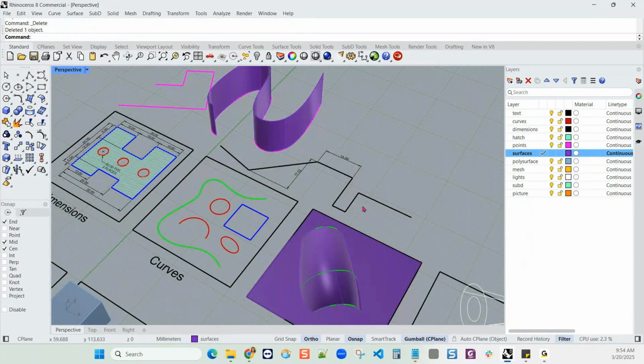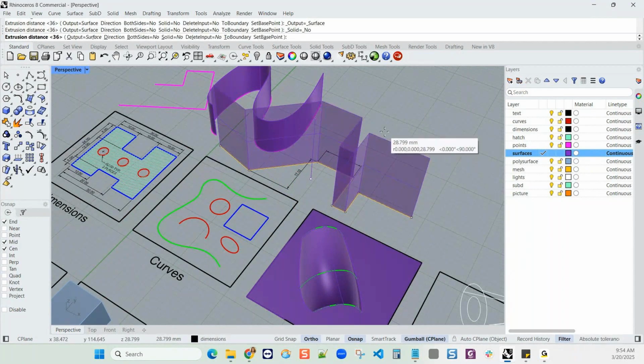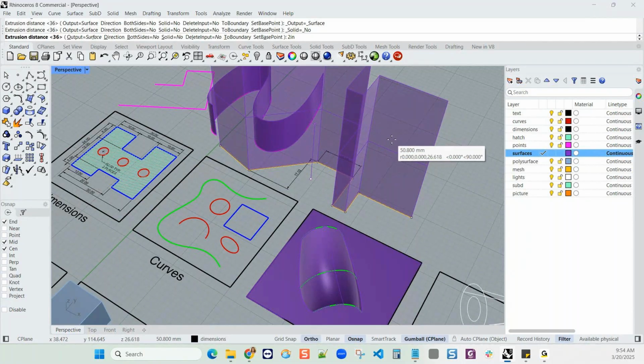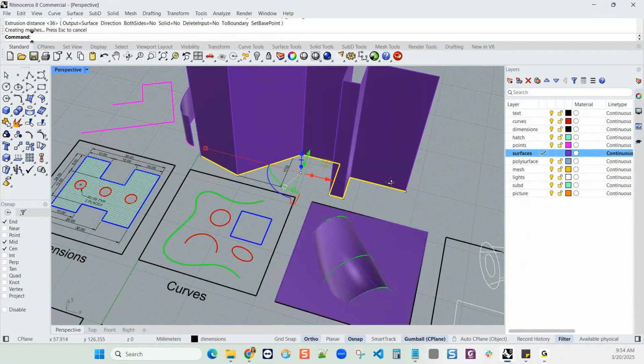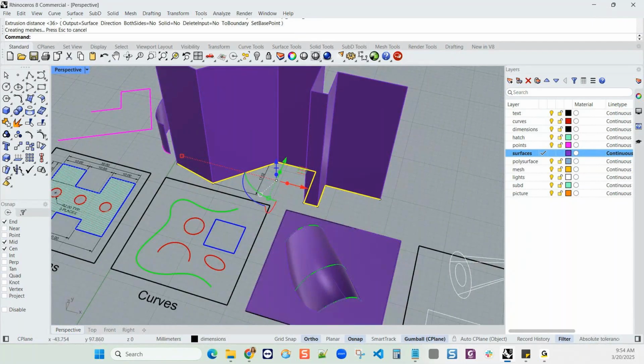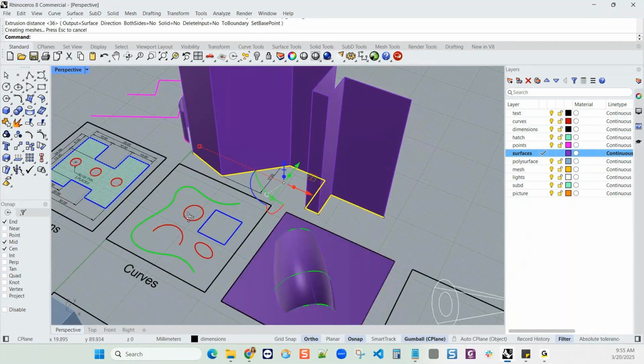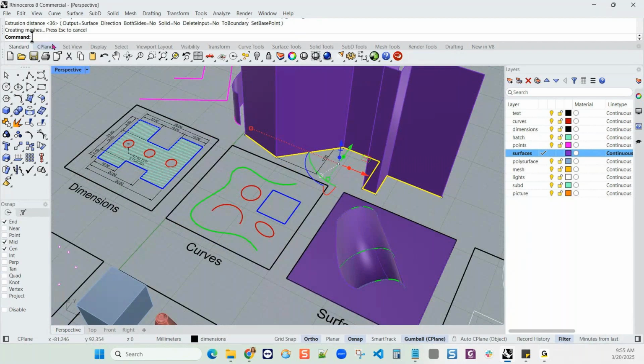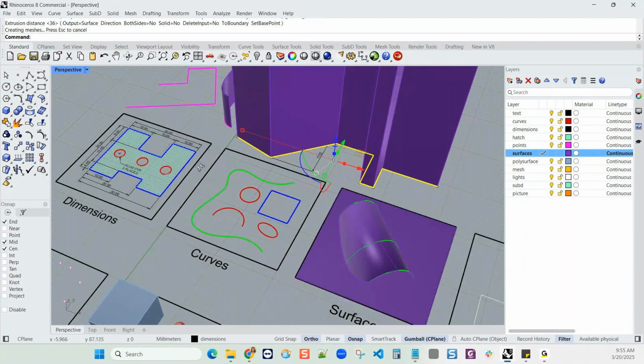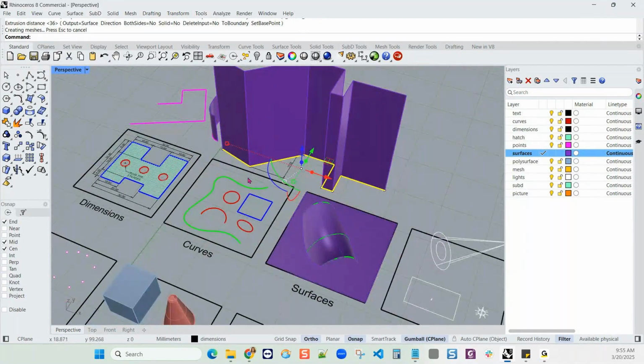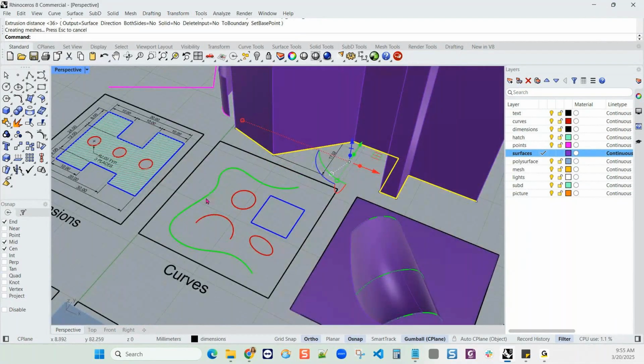I can extrude inches. If I type in 2 inches, either the inch mark or IN for inches, it will override the millimeters and convert that distance into inches. So anytime you're typing in a distance, if you follow it with the common modifiers, IN for inch, MM for millimeter, CM for centimeter, M for meter, it will override that distance with a conversion to that unit.